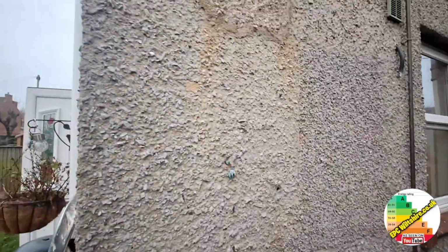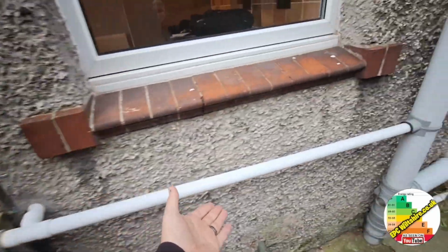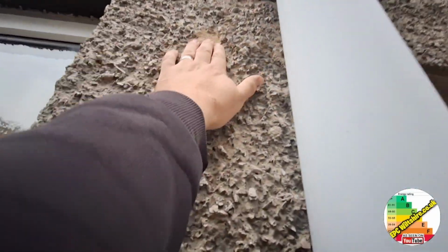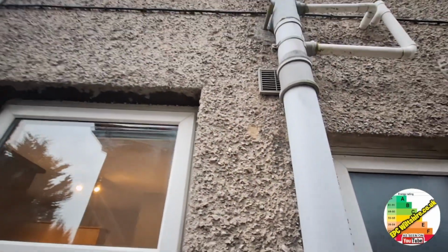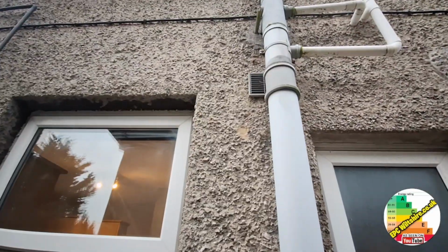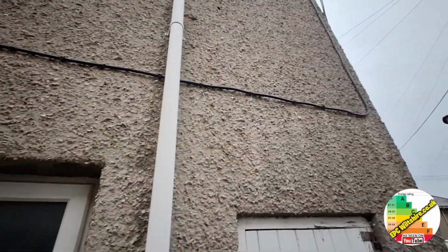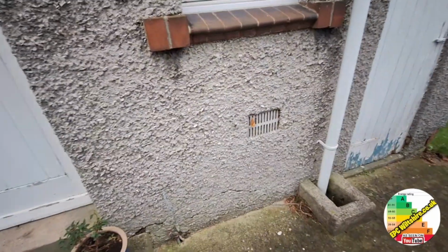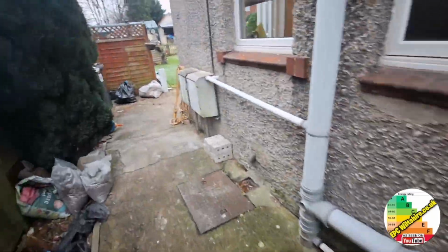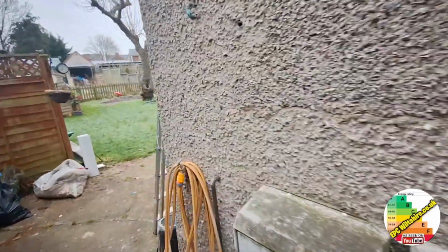Indeterminate whether this is a cavity wall or not, because we've got one hole here, but I'm not seeing a pattern. There's another hole here, and then nothing under the windows, so I'm not seeing a pattern of cavity wall insulation. But here's another one here, so that looks similar to the one over there. Let's get a picture of that one. And then if we keep going along here, we're not seeing any more. So it's quite indeterminate, really. But I've had a good look, and I'm still not seeing a pattern. So I'm starting to think as built.